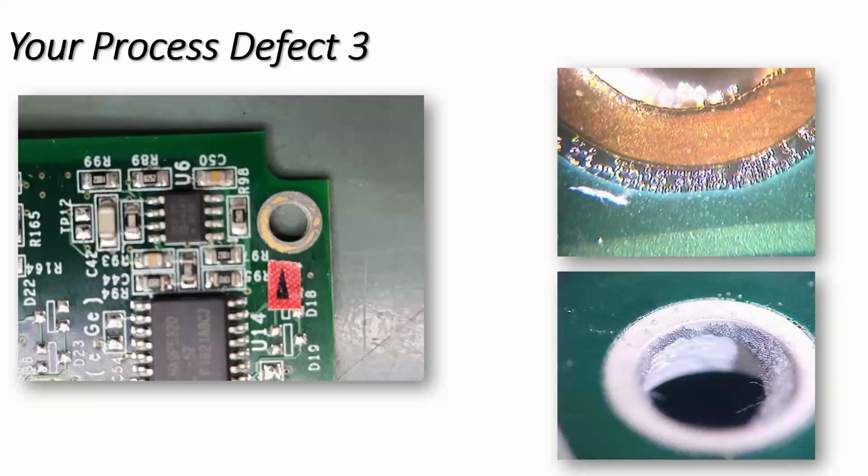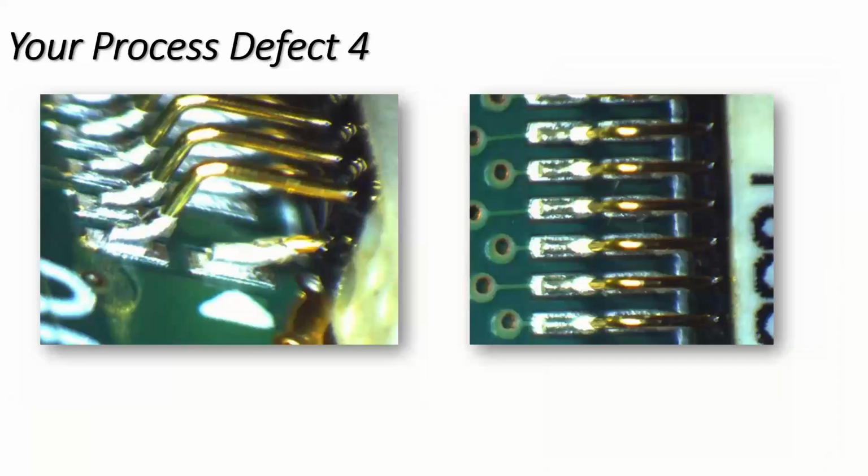And if I was talking directly to the customer of the contractor in this particular situation, I would say 2 things. 1, accept the product as long as it's going to not affect the functionality and mounting. However, I would insist that the contractor do something about his controls in his process, and also perhaps learn how to clean boards off correctly and properly to eliminate paste residues being left on the surface. So I do sort of 2 things I would suggest in this particular case.